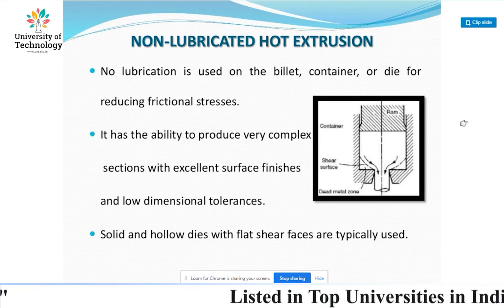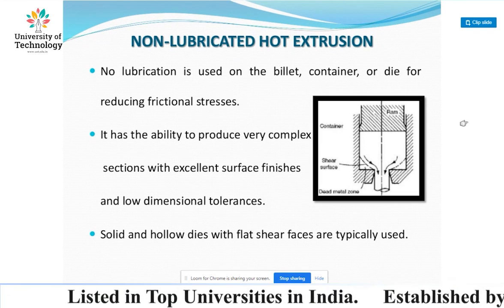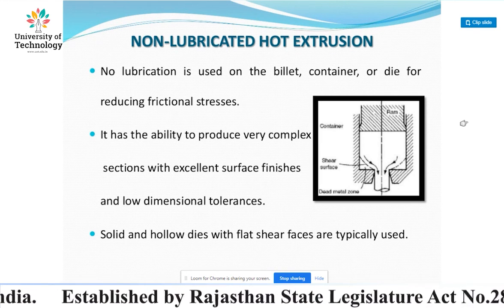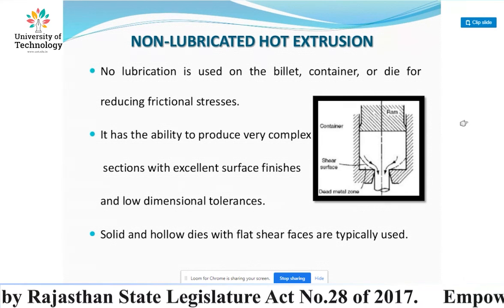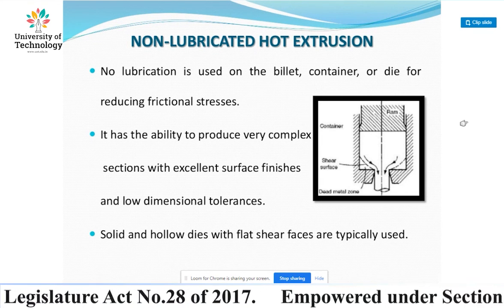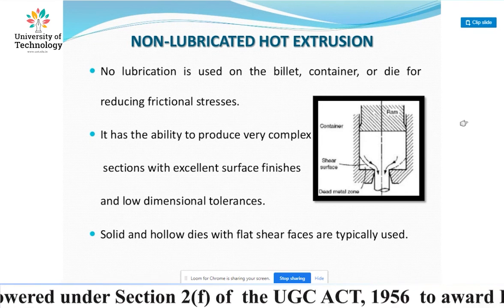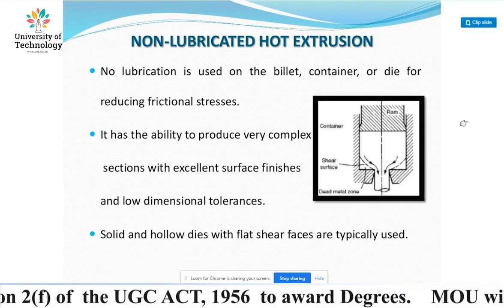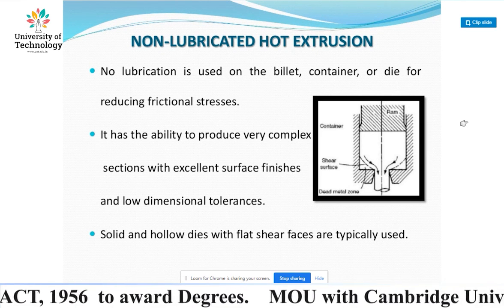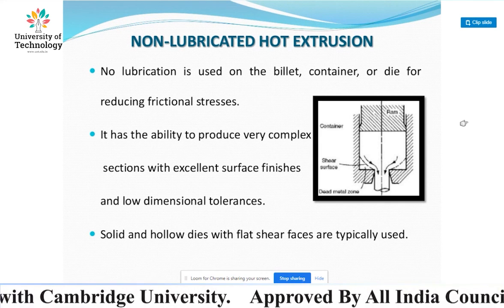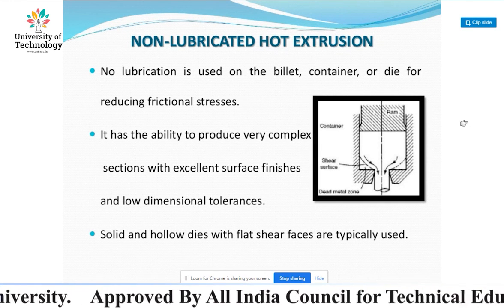Non-lubricated hot extrusion. No lubrication is used on the billet, container, or die for reducing frictional area stresses. It has the ability to produce very complex sections with excellent surface finishes and low dimensional tolerances. Solid and hollow dies with flat shear faces are typically used for the non-lubricated hot extrusion process.